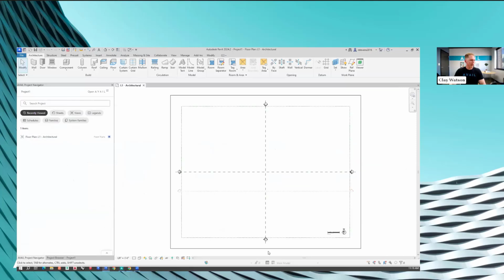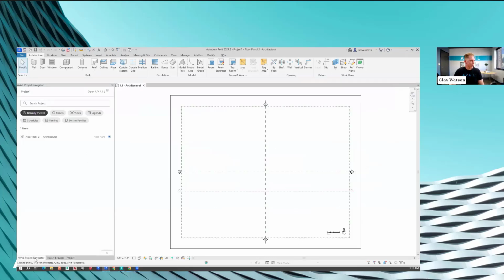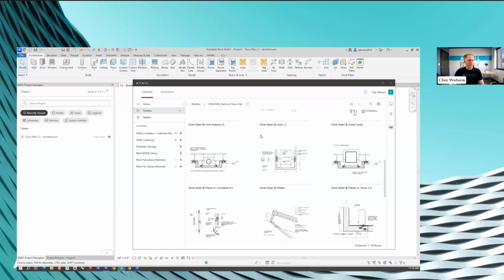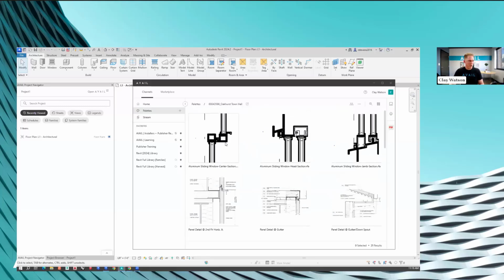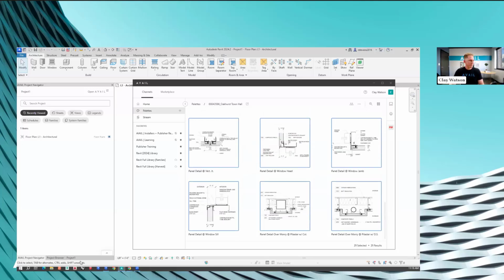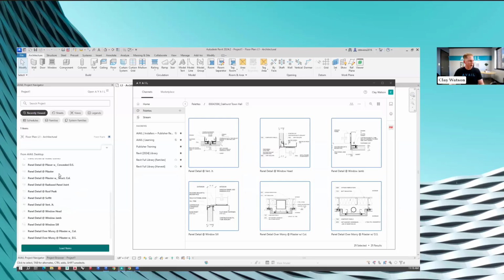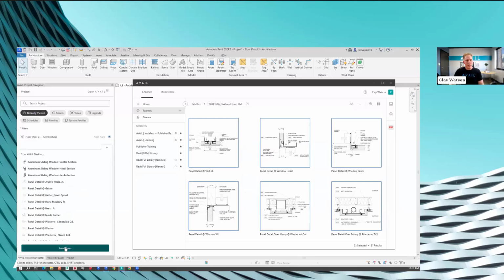and I've got my project navigator docked beside my Revit browser, if I've got that selected, I can actually go in here. You can select one, and that's fine. But you can also do a Control A. You can select all of them at once and give Project Navigator a second, because there's a lot in here. It's 21, and bam, I've got them all loaded up, ready to go, and I can load them directly from the Project Navigator interface.